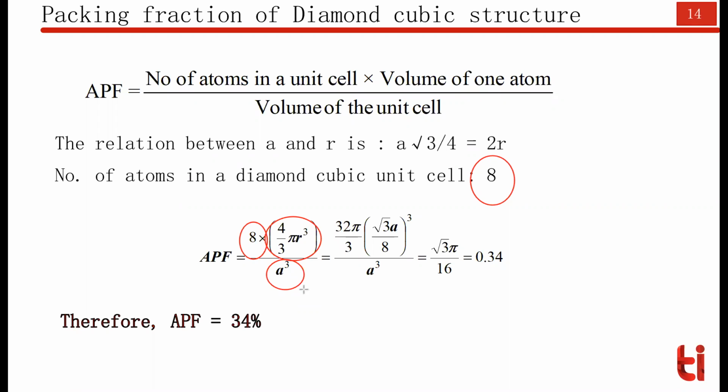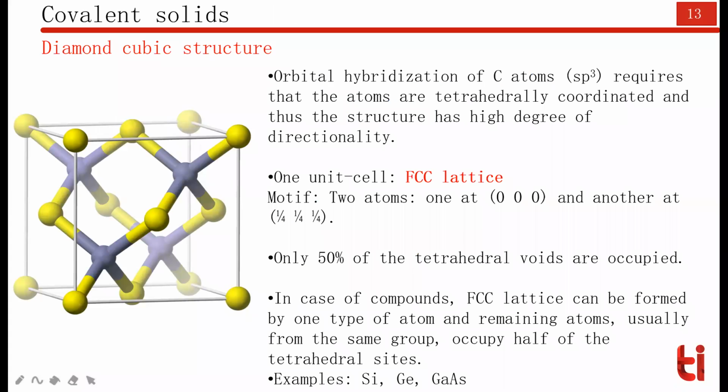density of atoms. So if I go back and show you the unit cell, you can clearly see that the direction with the highest density is the one along its body diagonal, because along the body diagonal you have the highest number of atoms occupying their positions. So we know the length of the body diagonal, which I have just shown here, is equal to root 3a.